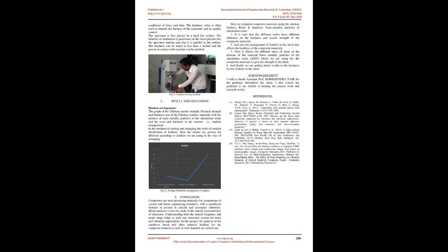B. Flexural test. The specimen is cut into the required shape. The shape taken for the flexural test is rectangular. The cutting is done with the electronic machine. Then the specimen is taken to the flexural testing machine. Then the tool is attached to the two-point machine. Then give the required power supply, the machine starts working, the tool moves towards the specimen and the specimen breaks at a certain point, and the reading is taken through the computer.